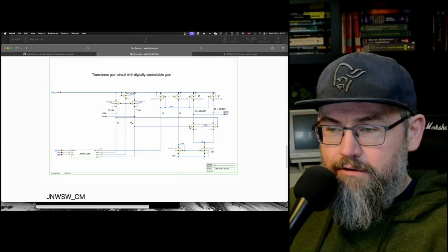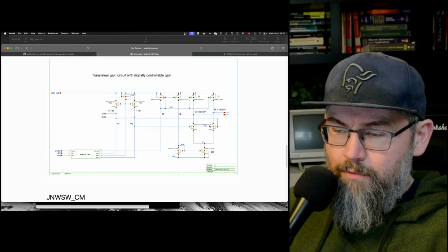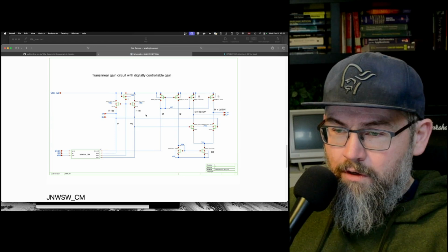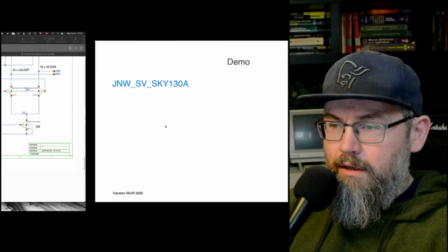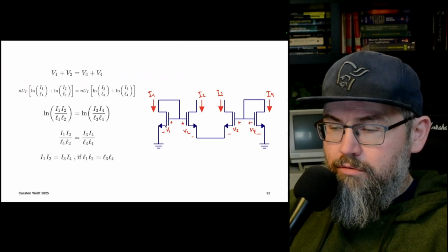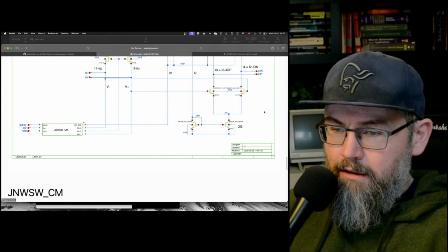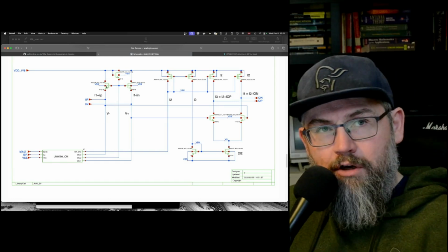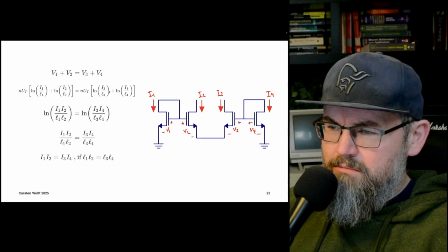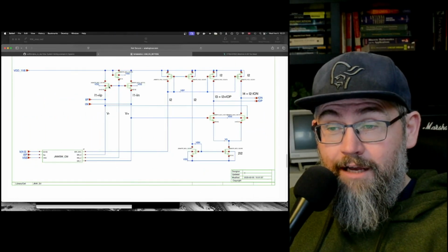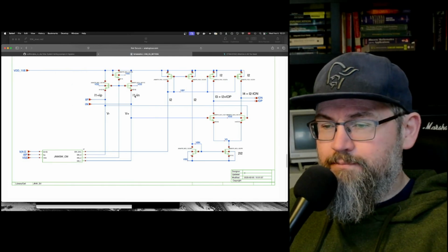We're not going to look at the translinear circuit that is shown here, but notice that we have a diff pair at the output. Actually, let's quickly look at the configuration here. In the picture that I showed you, we have two diode connected NMOS on both sides. In the picture that I'm showing you now, I don't really have diode connected NMOSs. I have NMOSs, but I'm injecting the signal at the source. That's pretty much the same thing.